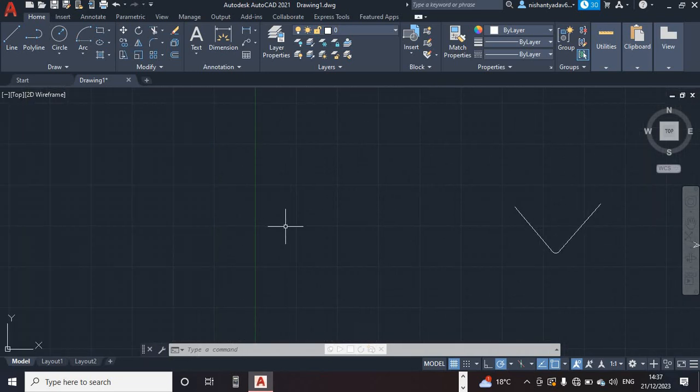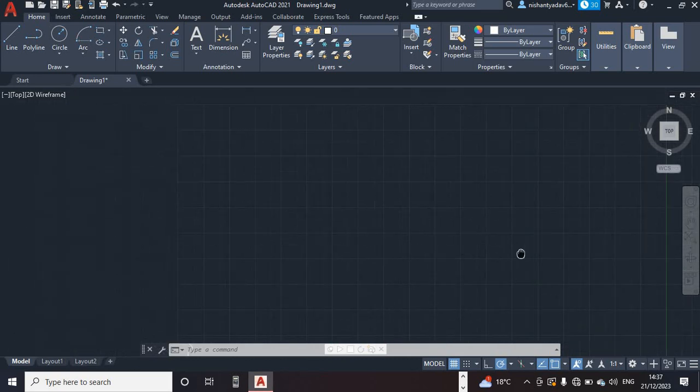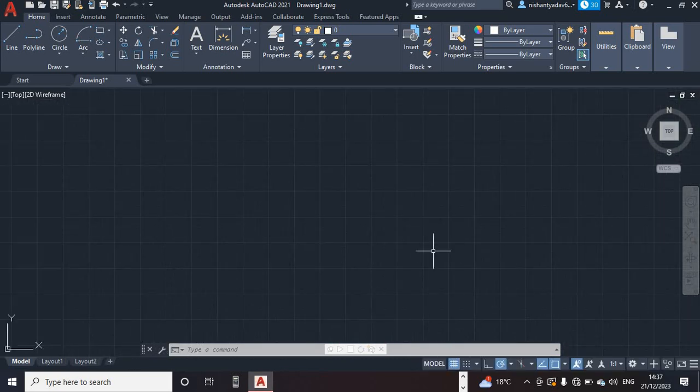And the next command is extend, and it is used to extend the selected boundaries or edges. Suppose I have here, I will press this 90 degree. After pressing this option, ortho, this is the ortho option. After pressing this ortho option, if you draw a line, then it will be drawn in 90 degree only. It means a straight line only.